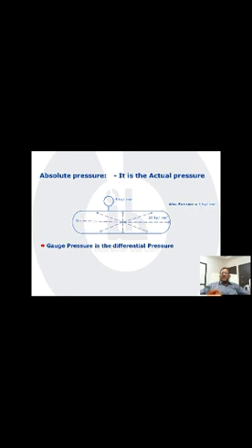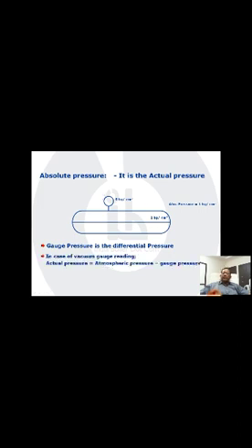You understand it in a better way when, at the starting of the boiler, you take the normal drum level, you do not put heat, therefore there is no steam inside. What is the pressure inside? The pressure is same as atmospheric pressure, which is, let us say, 1 kg. And the gauge is going to give you a 0 reading at that time, because it is reading only the differential pressure, right? Now that's why I told you that absolute pressure as gauge pressure plus atmospheric pressure may not be correct all the time.